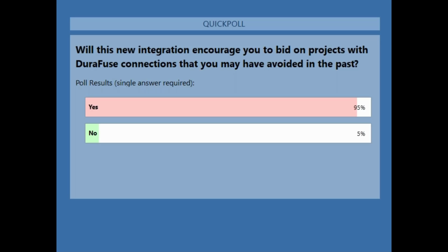The other benefit of that is during severe earthquakes, when the connection is undergoing those large deformations, part of the deformation is accommodated by slipping in the bolt holes. And so those long slots enable us to dissipate energy and achieve large deformations without damaging the beam. That helps in addition to the fuse yielding. Oh, good. Boy, I'm glad you're here to answer that question.